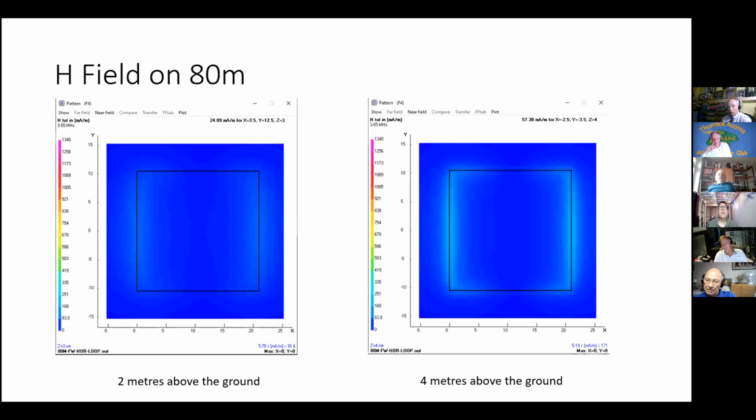You are perfectly entitled to plot the radiation pattern of your antenna and say the gain in the direction the public can get near it is not the 12 dB of the Yagi, it's more like 2 or 3 dB, or even minus something dB in one of the nulls, and use that to calculate the distance or the safety margin in that direction. That's a perfectly legitimate thing to do if you are able to document the antenna pattern.